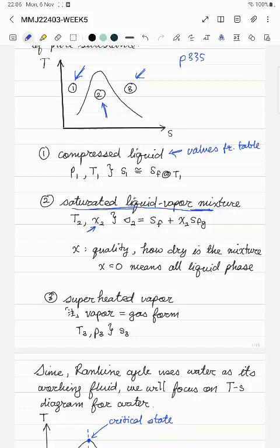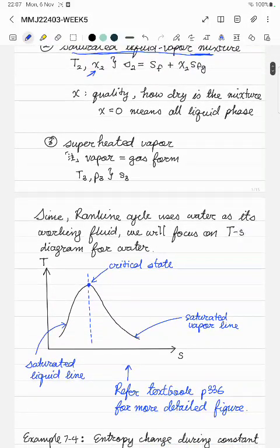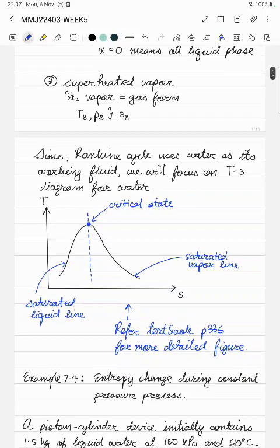And we also have table A6 for superheated water, and these are all computed for a specific range of pressure. So simply said, it is for a constant pressure process, and we'll look into how to use the table later on. But suffice to say, for the Rankine cycle, it's not as straightforward as your normal gas turbine cycle, so you have to rely on empirical values from the table, values obtained from experiment, to calculate its efficiency and power output.